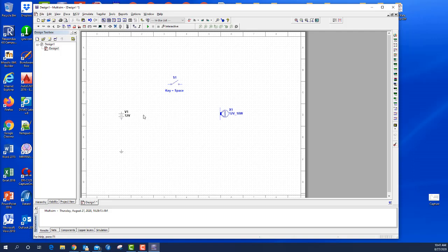And to do that, you just simply go to the wiring connections for each component, like so, and just click. Once you click, you don't have to hold it. Just click, and now your cursor is turned into a wire, and it's saying, hey, where do you want this wire to go? So I want it to go to the switch. Click, and then it puts it in place. It connects it. Go to the other side of the switch, click, go to the lamp, click. Then come out of the lamp, click, and go to the battery, click.